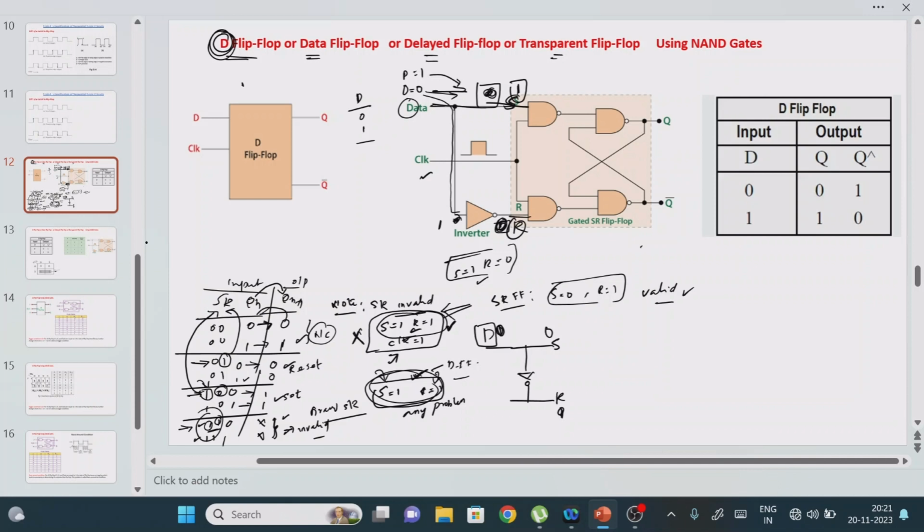Right, now we see what the block diagram of the D flip flop is. We have the single input, then we have the clock pulse, then the outputs are: one is the normal output, another one is the complement output, Qn as well as Qn bar. So this is the circuit diagram for the D flip flop. You short the S value and R value by using the NOT gate, so that it will become the D flip flop. The ultimate aim is that we should not get S equals 1, R equals 1. This can be solved by taking a circuit something like this, correct? Next we will see the truth table operation, then finally we will find the characteristic equation for the D flip flop, right? So that the operation of the D flip flop will be completed.